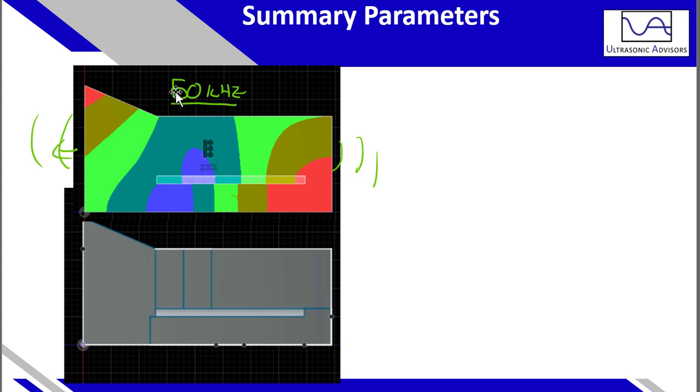Firstly, this is the dominant longitudinal mode. Usually, the first mode of resonance is the target mode of operation. That's how we traditionally, most often, design devices. So here in the high stress area, we put our piezo stack. That provides the best level of excitation.